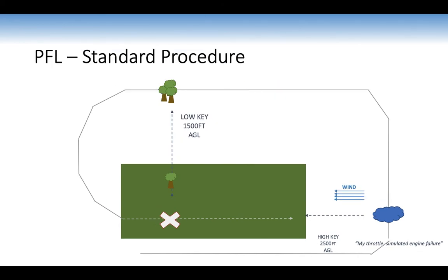Then at this point, you're going to do the 50-cent pattern. Remember, it's going to be almost like a glide approach, and your checks are done, so you can focus on flying the airplane. So it'll be that 50-cent pattern, where you're assessing that spacing with the wings level, and the aim point should be within that 1/3 spacing so that you can reach the field.